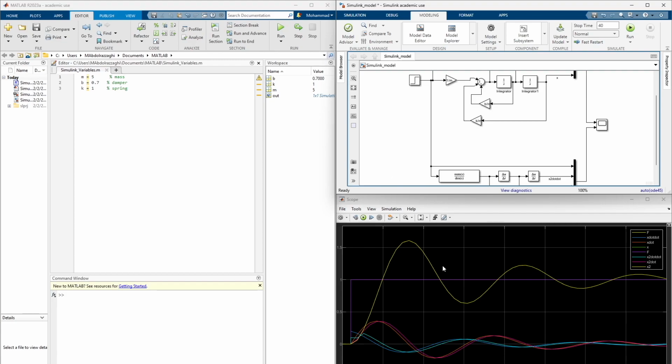the system response differently in terms of the overshoot value or the settling time, and all of those parameters that are important in calculation of this step response time, or the number of the oscillations that need to be spent to settle the result. So this is how a given system building block is going to be analyzed and simulated in MATLAB, and the parameterized .m file can be modified and coupled to the Simulink file so that we can run the Simulink model with given parameters